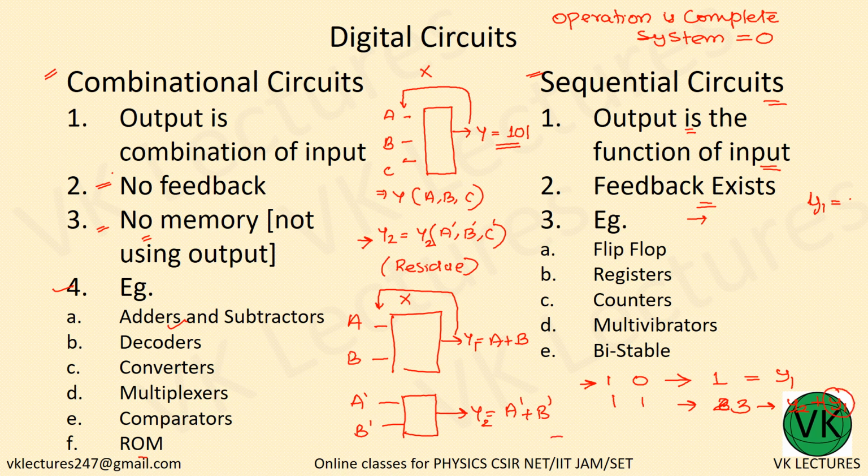Which means your next output Y2 will be a function of A, B, the present input, plus a function of Y1, which is the previous output. So the next output depends on the previous output. That is called memory effect, and that will be present in the sequential circuit.